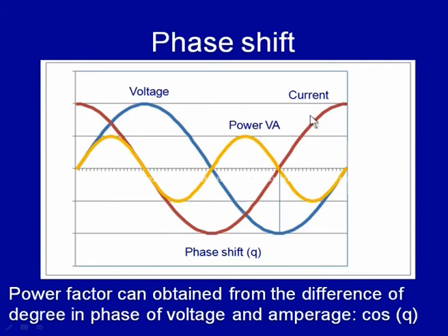The use of proper power factor helps to maintain the proper phase shift between the voltage and the current, so that when the current is 0, the full open circuit voltage is available, which will facilitate the release of the electrons as well as the flow of the electrons required for maintenance of the arc. So, these are the two methods which are normally used for proper maintenance of the arc when AC is used.